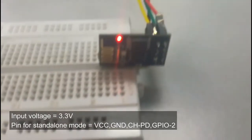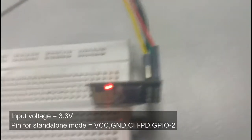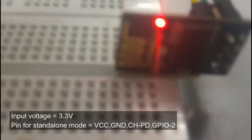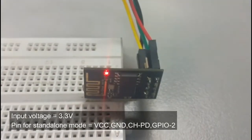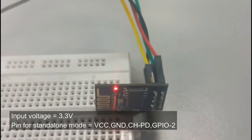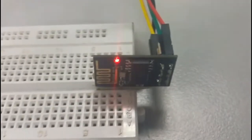And this is the ESP8266-01. We use it to send the data to THINGSPEAK after we get the values from the DHT11 humidity and temperature sensor. It uses 3.3 volts as input, and it uses only 4 pins to make it a standalone device. Standalone means that if we turn off the power supply, the code or source code still remains saved in this hardware.